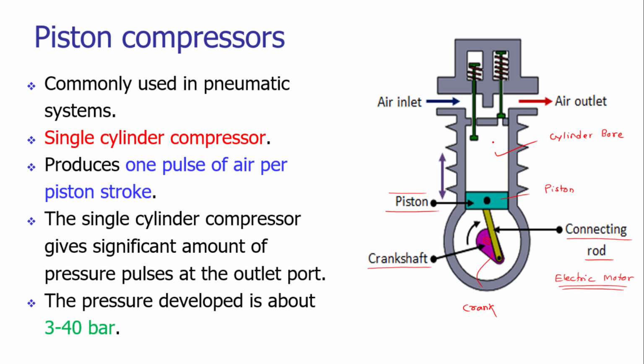So when the piston is moving away from the walls which are there on the top dead center, this is the TDC, that is the top dead center. There is a creation of vacuum here, a pressure difference from the atmospheric pressure, and due to that the valve will get opened, and when the valve opens, the air will be sucked inside the volume for the half rotation of the crank.